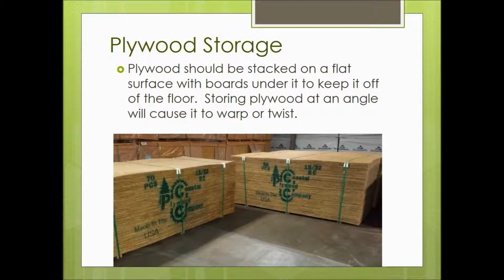You can see, if you look closely right here, there are some boards under this plywood that let the air circulate under that bundle of plywood. So you want to do that, and really take a lot of care when you store your lumber.